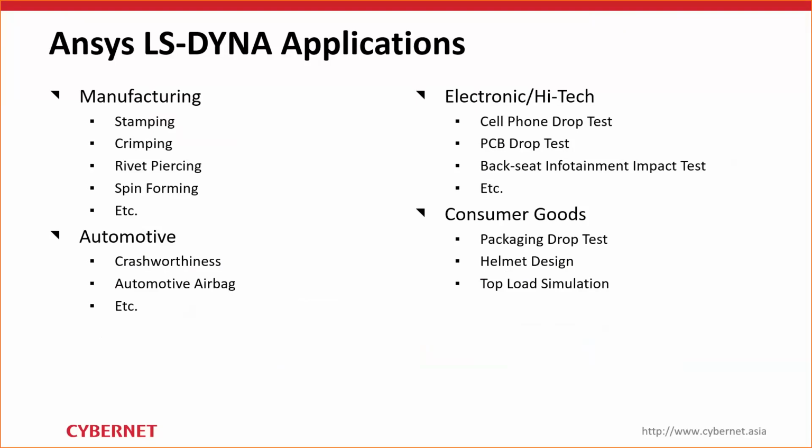This kind of application involves large deformation and also large plasticity, which is a very material non-linearity that happens there, which can be difficult or hard to analyze implicitly. It can be done, but the challenge would be far more significant compared to when you do it using the explicit